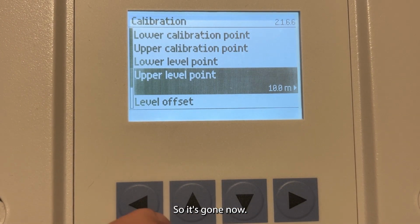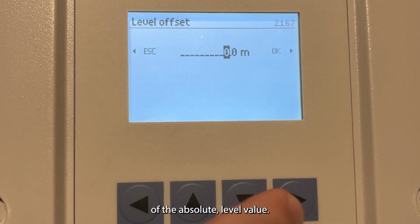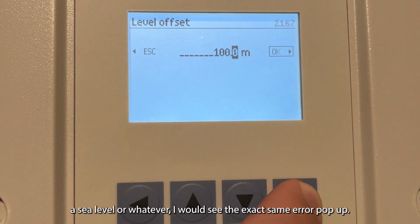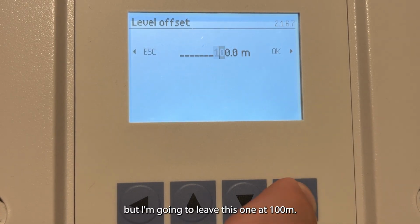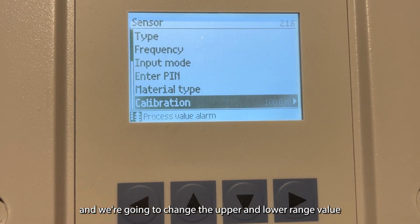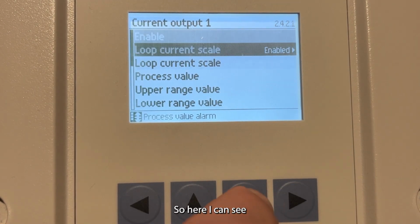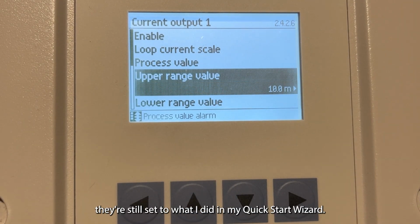So it's gone now. Again, we can do the same thing with level offset. So that just changes our reading of the absolute level value. So again, if I added 100 meters there as well, if I wanted to reference, say, sea level or whatever, I would see the exact same error pop up. So again, there's that same upper saturation issue, but I'm going to leave this one at 100 meters. So this time we're going to go back through and change the upper and lower range value in our inputs and outputs of the milliamp output. So here I can see what my upper range and lower range values are, and you can see they're still set to what I did in my quick start wizard.